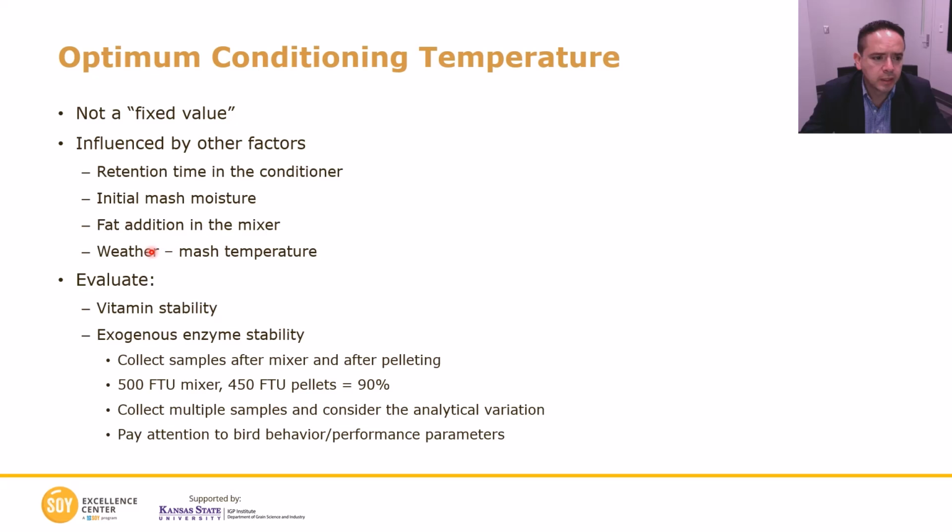In addition, you need to consider the amount of fat addition in the mixer. I told you that fat works as a lubricant, so if you have more fat in the meal, then the system is going to be able to tolerate a higher temperature without plugging. Also, weather can make a difference.